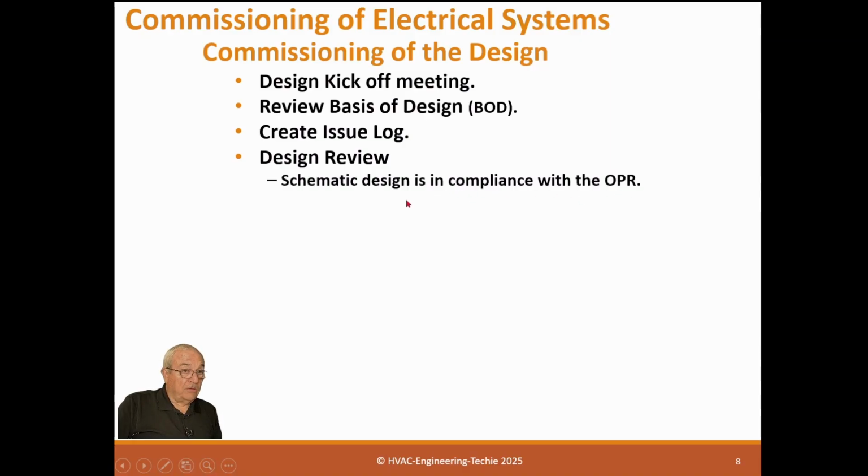So number one thing you're looking at, does this design work? Now, normally in commissioning, we have several design reviews. You can have a 35%, 65%, 95%, and 100%. Normally, we only see a 65, 95, and 100. If you have a 35, basically that's just to look at the schematic design you gave the owner when they were proposing a system, so it doesn't include much meat.